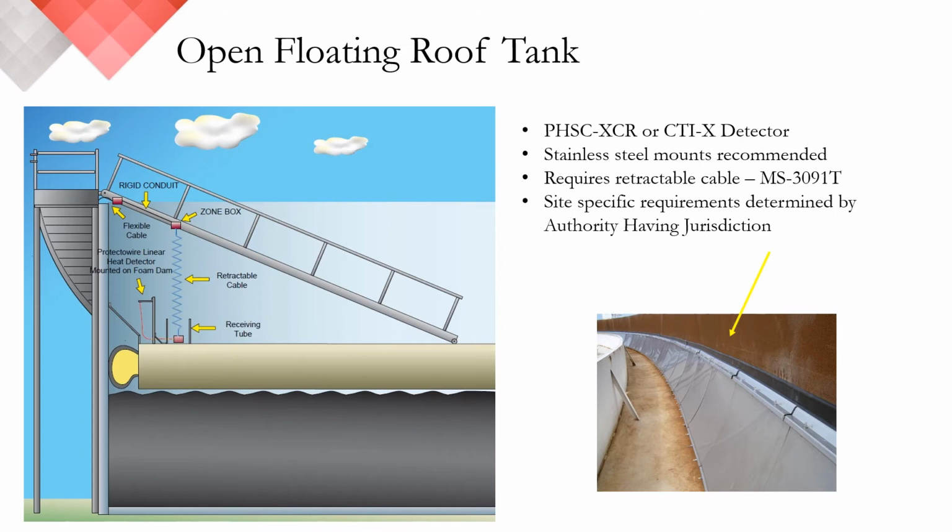This is a great cutaway. Again, thinking about the control drawing, all the control equipment is outside the hazard, and you're going to be using the PHSC XCR, or if you're using the CTI series, you will be using the CTI X. Stainless steel mounts are recommended in this kind of environment. Again, we're going to show you the retractable cable, the MS3091T. And as always, site-specific requirements are determined by the authority having jurisdiction.